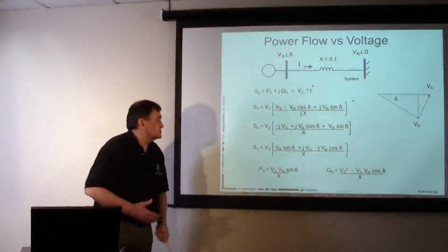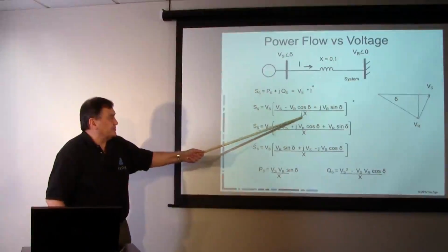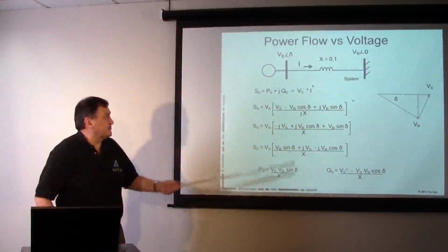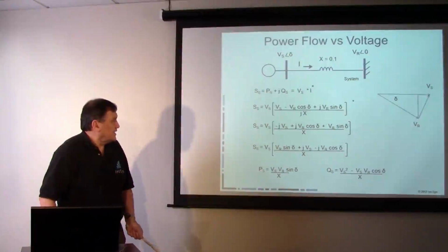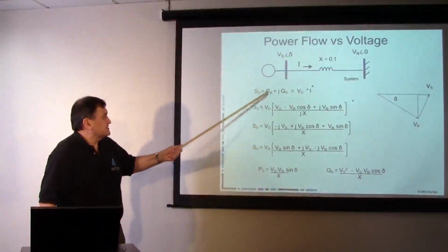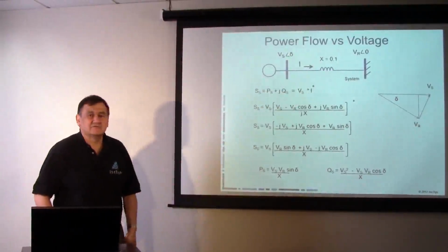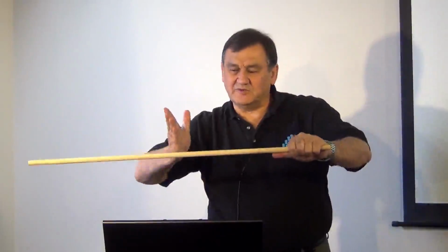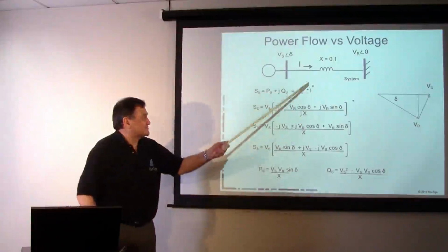So what we're doing is taking a voltage difference, dividing by impedance, and getting a current. Again, we won't go through all the detail, but that's the fundamental derivation. Our complex power, S, is the voltage times the current. Now we actually use a conjugate. Remember where we talked about how we have a lagging power factor where the voltage is lagging, but we want that lagging current to produce a reactive power in that direction, because reactive power flows to loads. That's why we have this little symbol here.